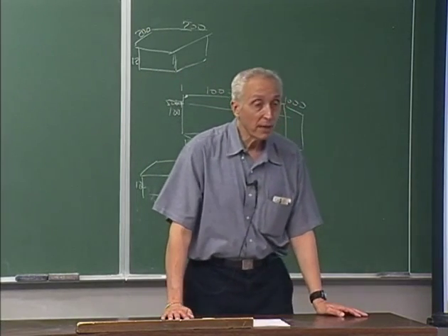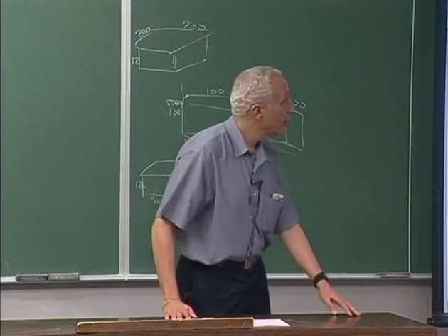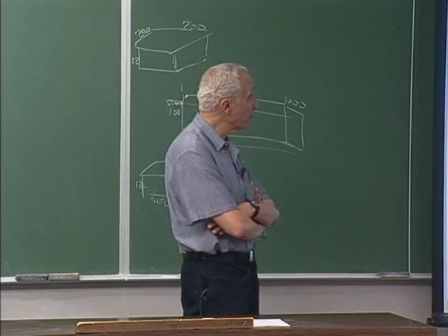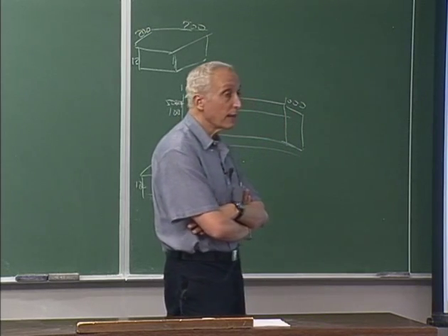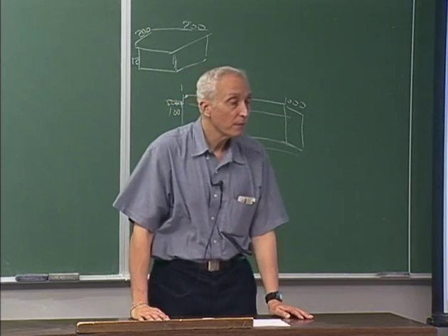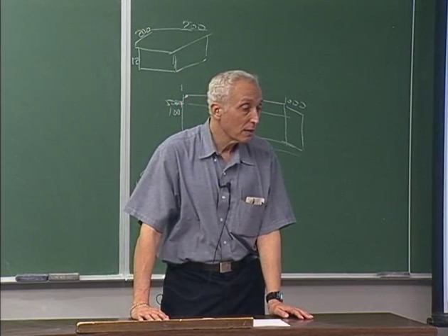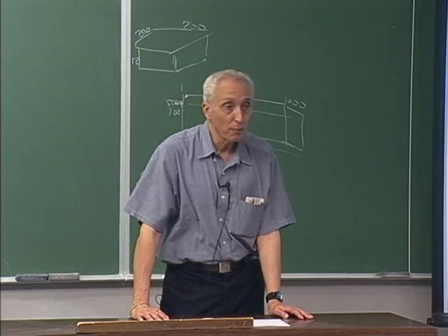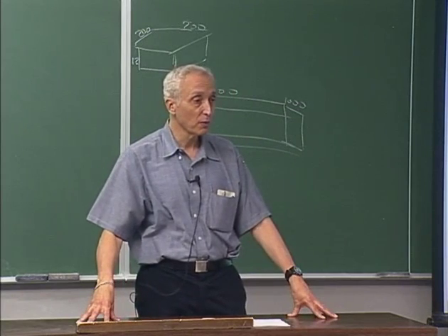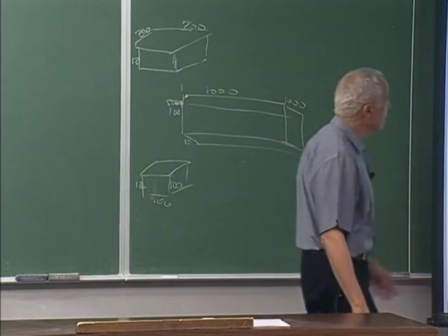To make for commonality between vibration and buckling, I'm writing the eigenvalue problem as (K - μM)u = 0. K is the stiffness matrix, and for vibration M is the mass matrix. For buckling, M would be the geometric stiffness matrix. If you didn't take a finite element course where you learned about those quantities, just take my word for it,